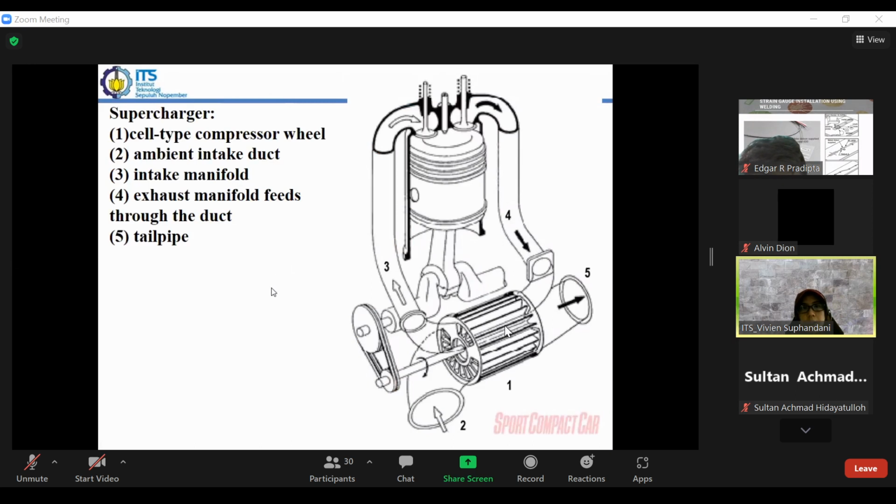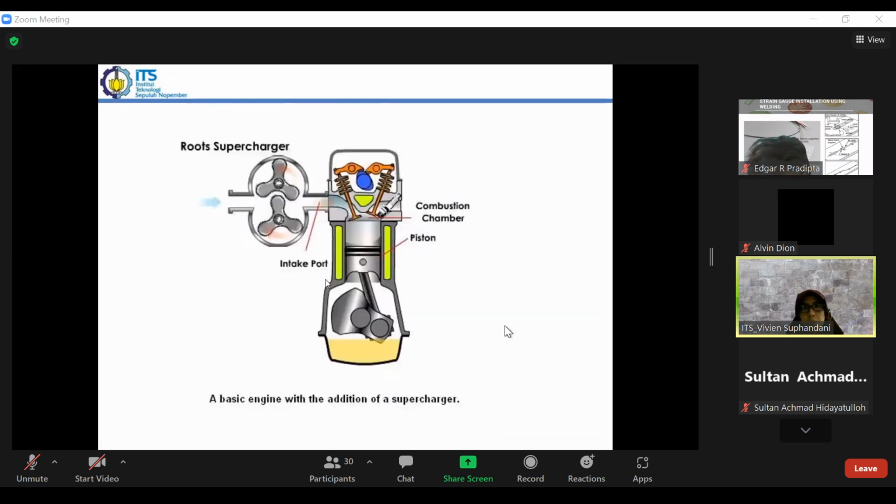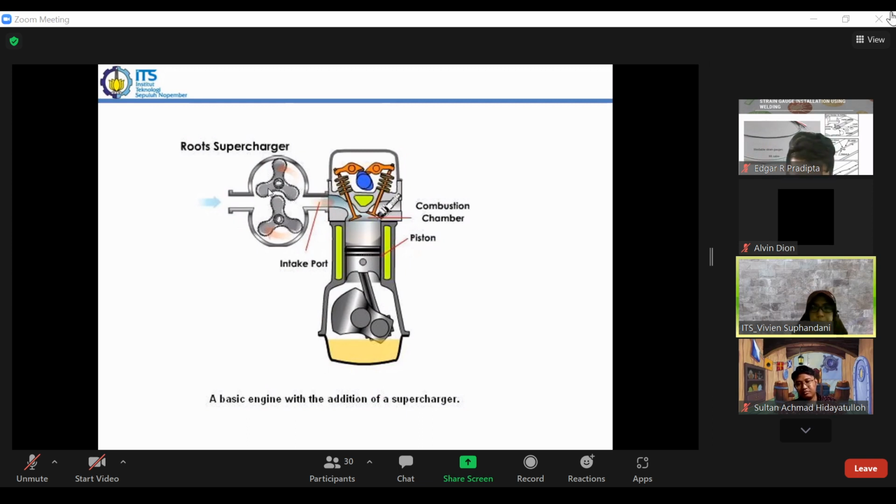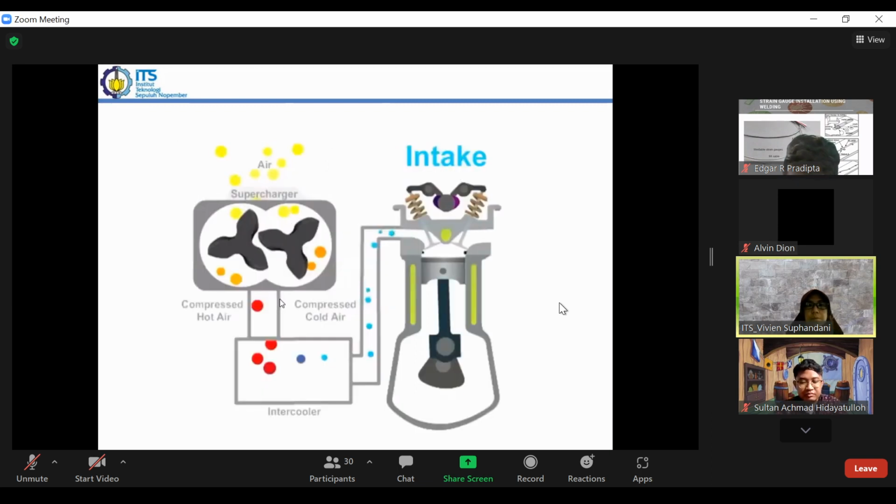Okay, so this is similar. I think that will be the explanation for the diesel engine. We have a slightly different shape here in which we have the supercharger. It looks like a gear, for example. We can use that as well. This is called a Roots supercharger. This is for a diesel engine, where we can have an additional part similar to this one as well, to reduce the temperature. We can have an air cooler or use an intercooler like this one.